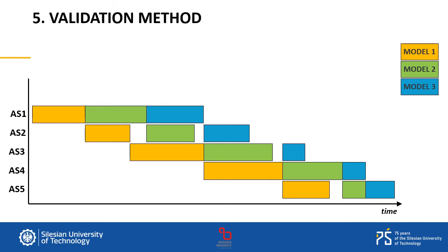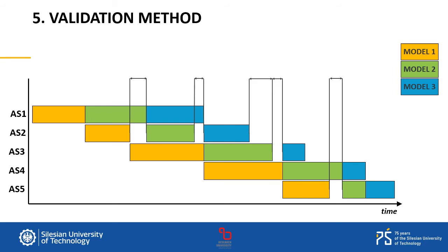In the production schedule of an assembly line, where we define a sequence of production orders, gaps between operation blocks can be noticed. In the case described here, the gaps can appear for two reasons. Either the workstation is waiting for a part from the previous operation, or the next operation is blocking the station from handing over the finished product.